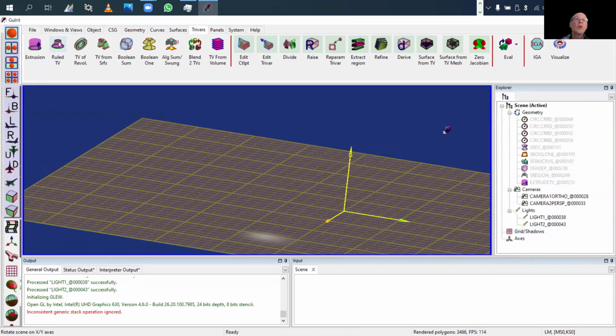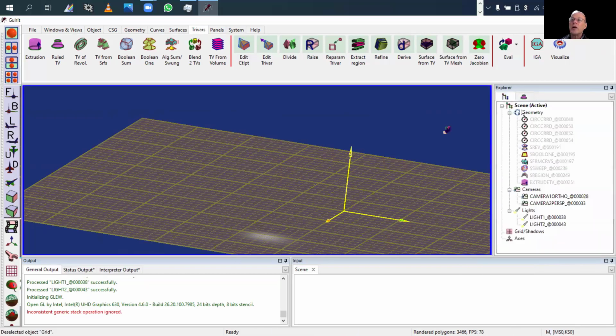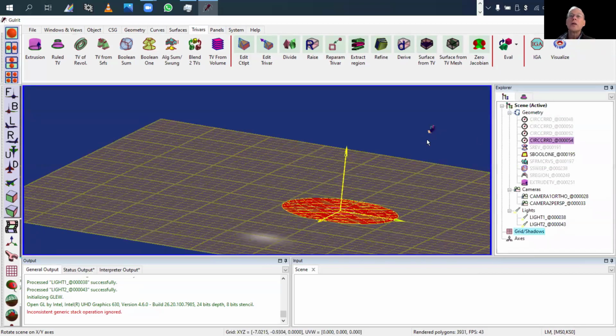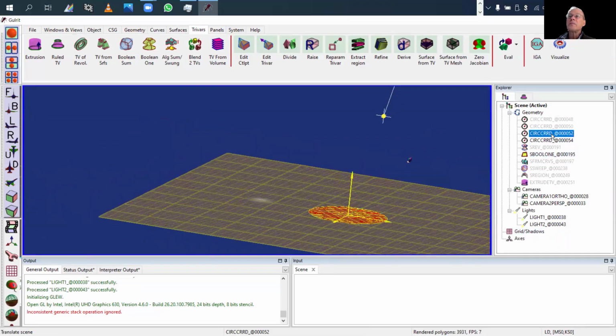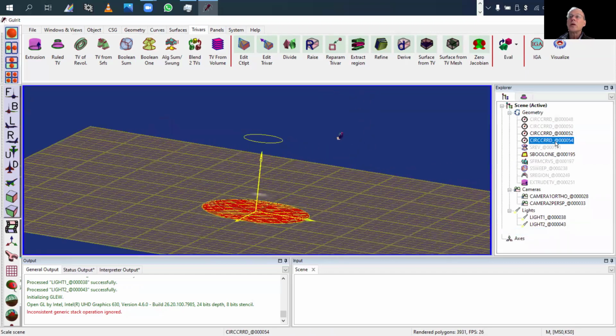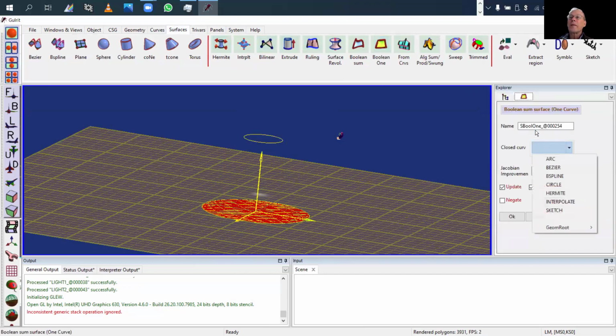Okay, and similarly, I can do a ruled volume of that. So if I select the first surface, now I need two disks. It's going to be challenging, but let's do two disks. So we have the Boolean 1, this one. Let's do Boolean 1 on this circle too. So we need circle 52. Surfaces, Boolean 1, 52. And so I have two disks.